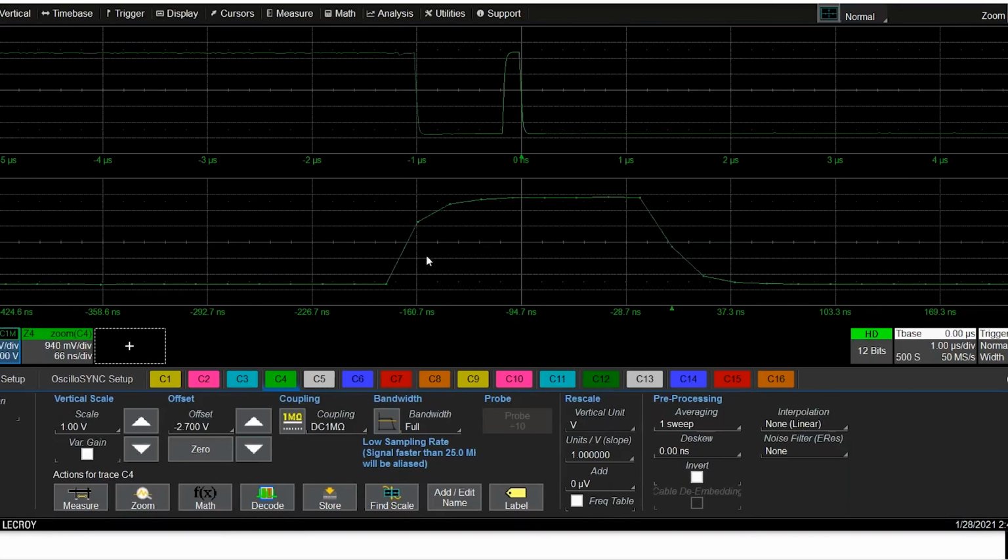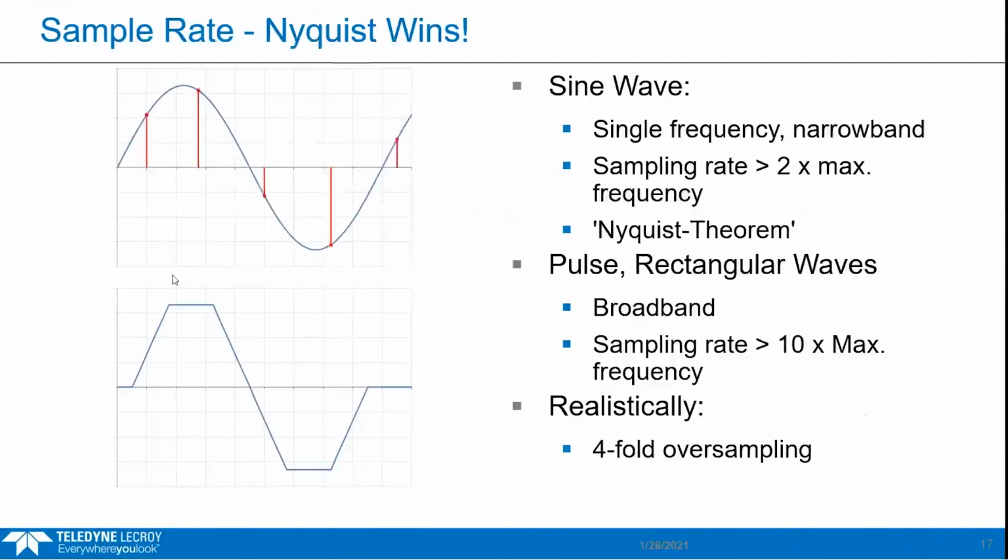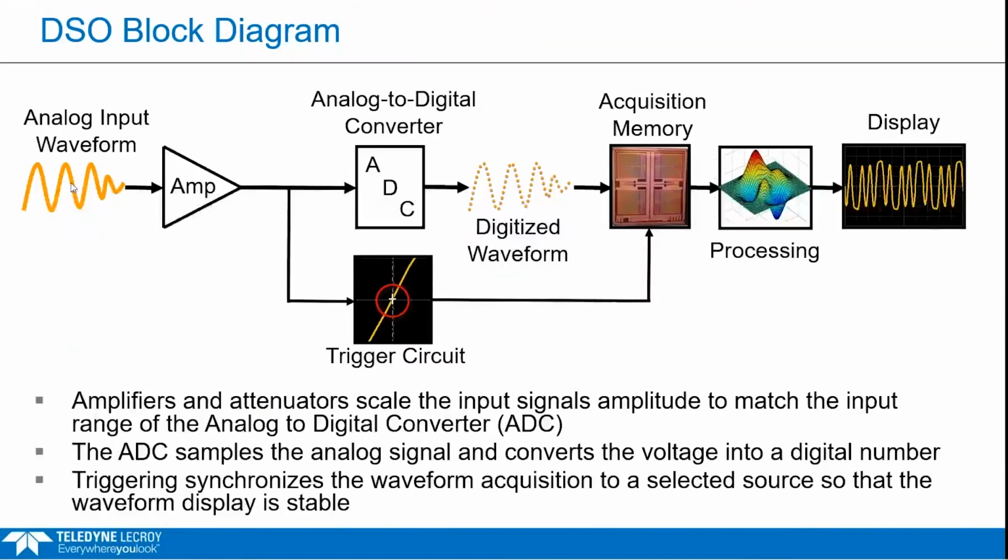And how do the 1x and times 10 probes play into your attenuation? Yes, it does. On the front end, if I go into the PowerPoint, what we're trying to do is get the right signal into the amplifier in the BNC. If it's really large, we've got to attenuate it, otherwise the amp can't handle it. It depends also whether we're 50 ohm or 1 megaohm input impedance as well.